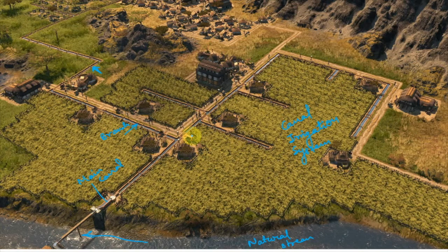If it is supplied directly to the field, for example, as you can see, this was the main canal, and from the main canal only you are taking the direct supply to the field. So this last part of the canal system, which is taking the water directly to the field, that is known as the water course, or that is also known as the field channel. Now that was a real image just to show you how this canal irrigation system works. Now we will look at the layout system of this.